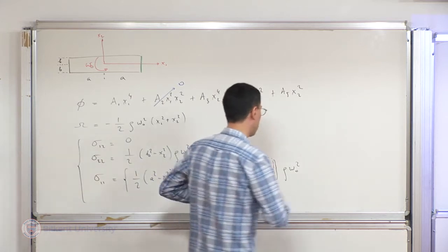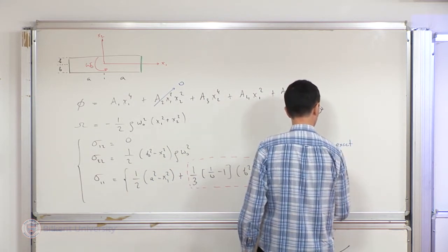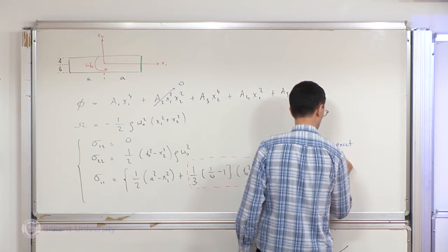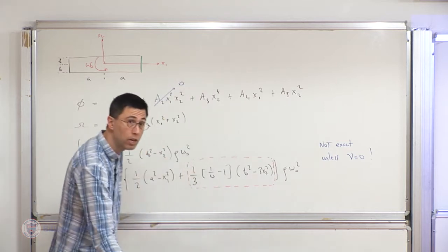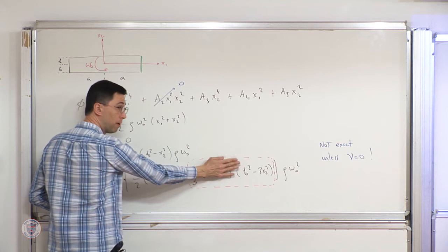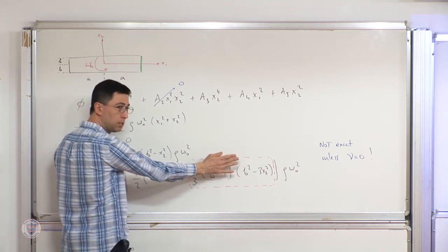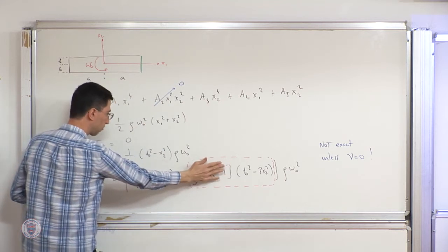unless the Poisson ratio is equal to 0. That's also something we concluded. And in particular, if it is equal to 0, and if you omit that term, you satisfy compatibility, all the boundary conditions, and everything with this Airy stress function, and the resulting stress field is that.